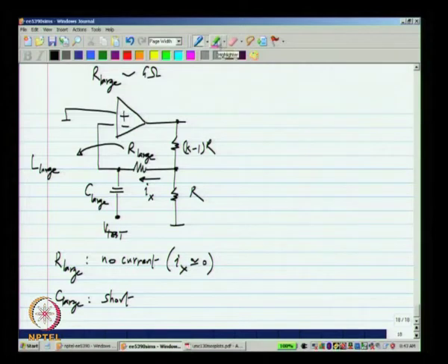Okay. Now, assuming that you have a MOS transistor circuit, the current here is usually 0. In that case, you can use a resistance. If the current here is not 0, let us say you use a bipolar transistor or some other MOS circuit where the current in this branch where you have broken the feedback loop is not 0, you use a large inductance instead, okay, because then there is no drop across the inductor at DC even if there is current flowing through it. Okay. So, you could use resistance or an inductance. The idea is to have the loop closed for DC.